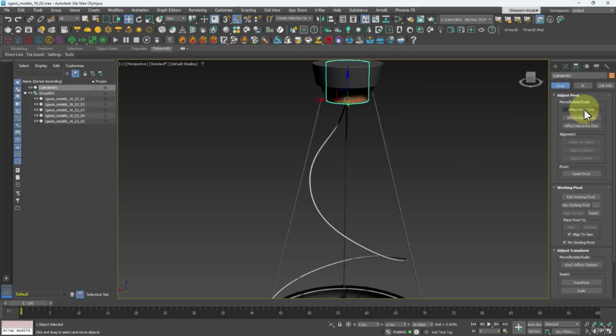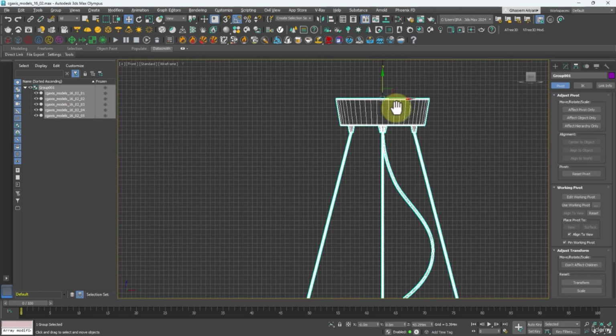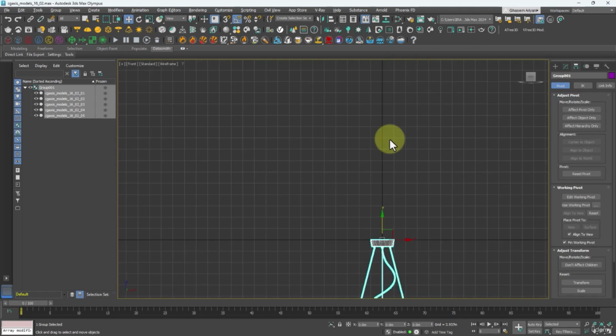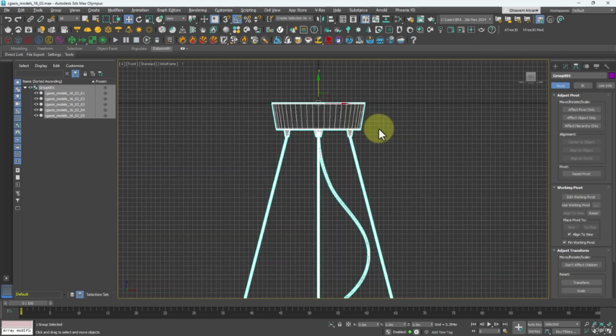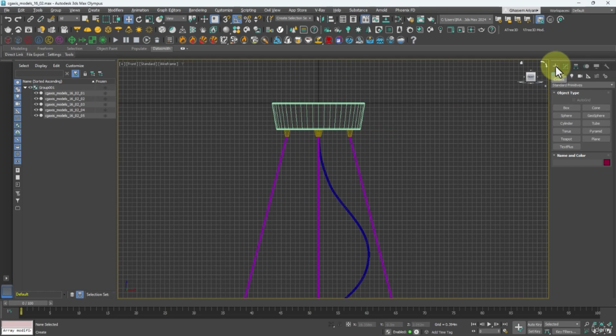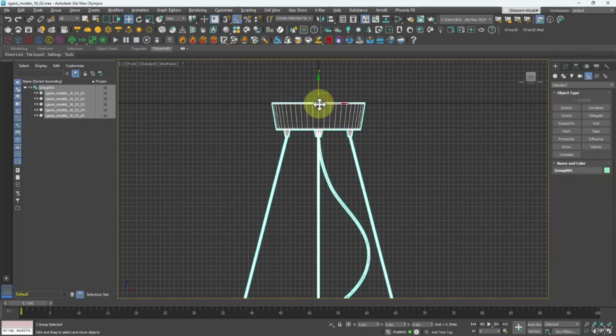Check the position of the gizmo. I can click on move and then set 0 for the coordinates and fix it. It is done. Then I want to check its height or the diameter. Here we got several methods. So here from helper, I click on tape. It is to measure the distance. Watch this, 7 meters. We need it to be 7 centimeters, not 7 meters.